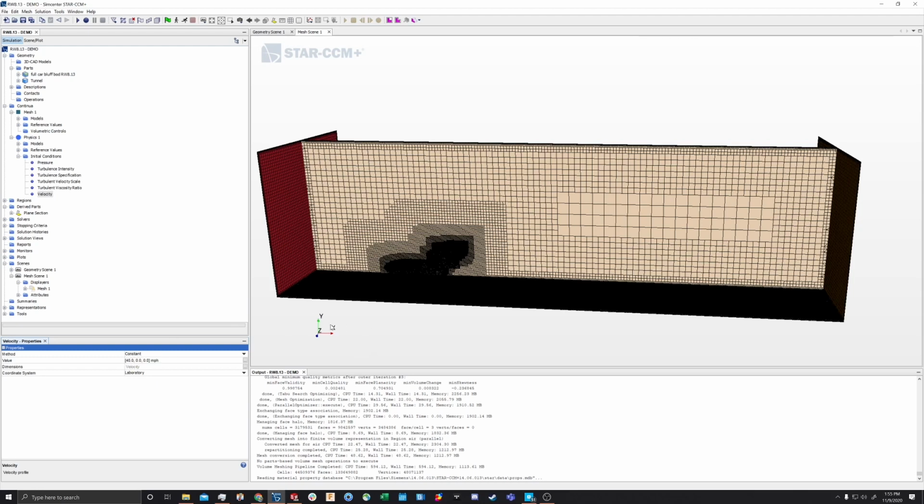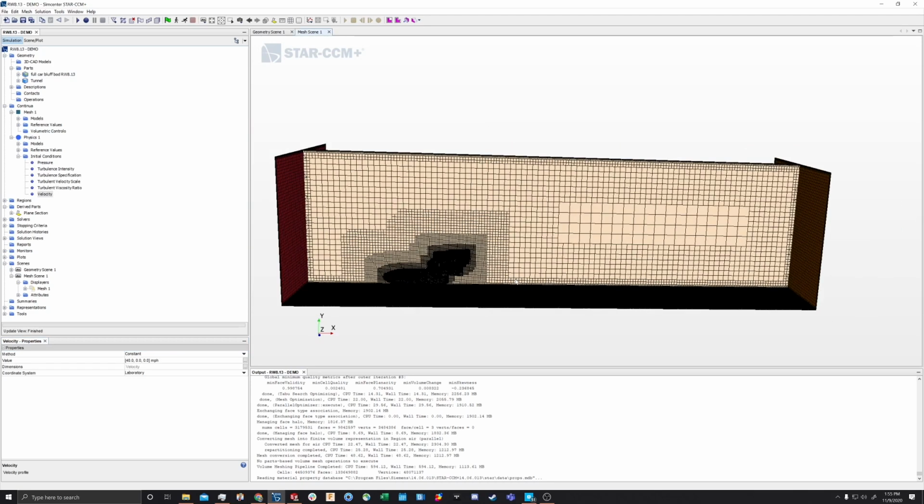But yeah, as you can see, we want flow to move from this. The inlet here is red, outlet is orange. We want it to move from the inlet to the outlet at the speed that we want to use, in this case 40 miles an hour. You can set that to whatever you want. You can also specify the units here, so you just type in miles per hour, meters per second, kilometers per hour.